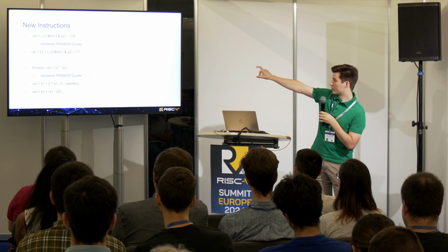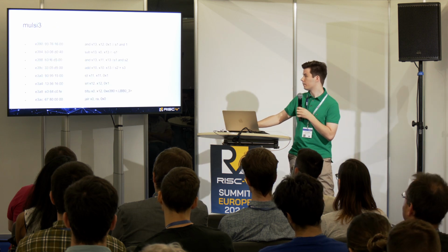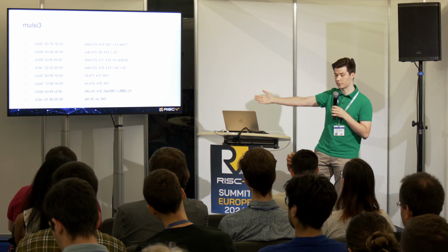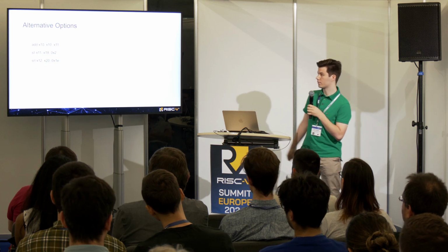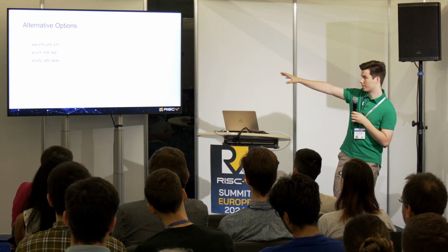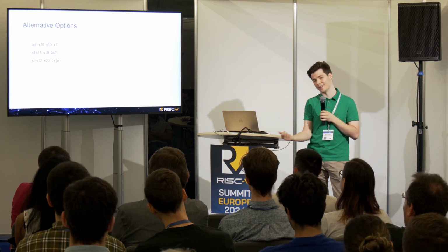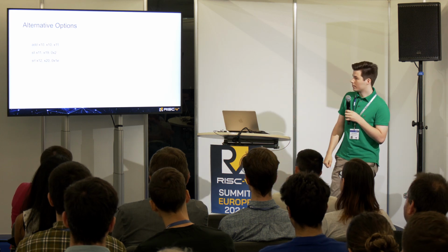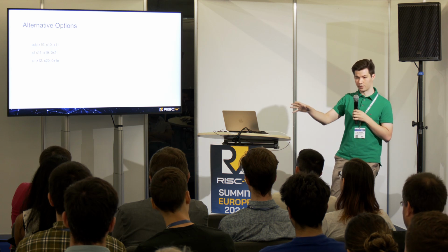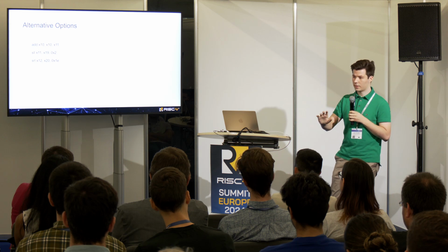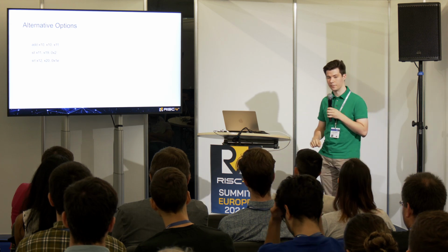The top two are the two instructions I devised based on the profiling I did previously, which somewhat reduced the cycle count, but obviously not as much as the multiply accumulate instructions. I also found a number of other promising candidates for new instructions, but the main problem was that most of them wrote to more than one register, so I couldn't really put that into a new instruction. But it tells me that the hardware would profit from being able to write to multiple registers, multiple addresses in one instruction.